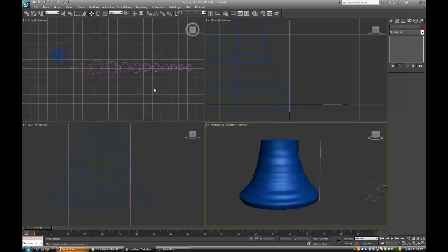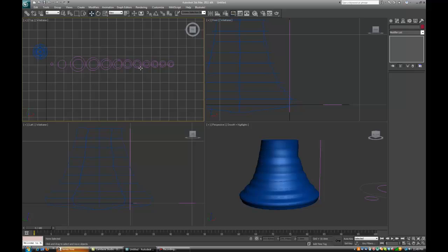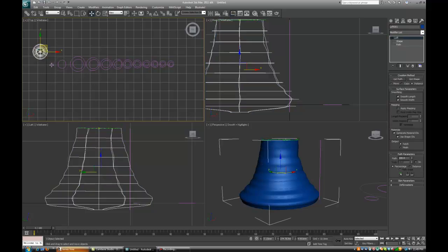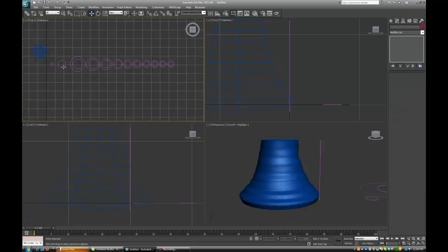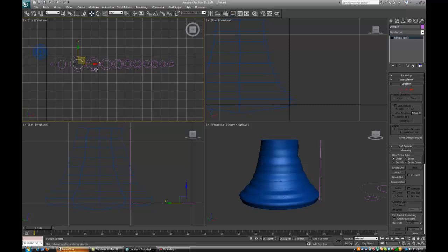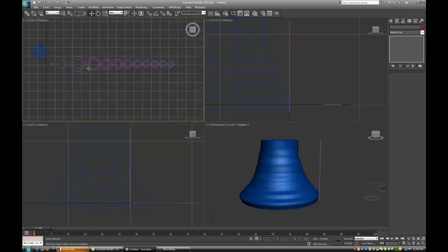Another thing that I may point out is when you are making your sections, your loft model, make a single loft for the exterior component, so these elements of the plaster sections, and then make a separate loft that deals with the inner ones, because eventually there may be some complications and it's much easier to deal with having a separate loft for each element.